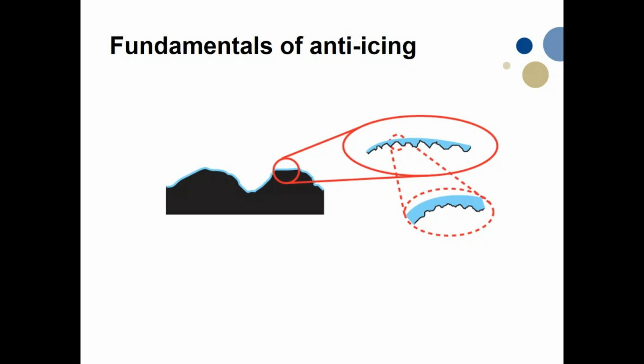So a pavement is a rough surface on different levels of magnification. And that roughness is very important for friction, because a rubber tire will just deform when it's pressed against this rough surface, and the rubber and pavements are gripping into each other, and now we can create friction, accelerate and brake.